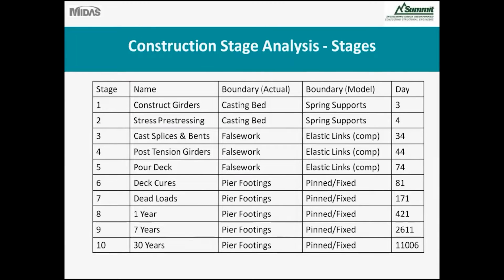On the construction stage analysis, in stages 1 through 10, we constructed the girders, stressed them in the bed, then erected them in the field and cast the splices and the bent caps. Post-tension, poured the deck, allowed the deck to cure, superimposed the dead loads, and then aged to 30 years.